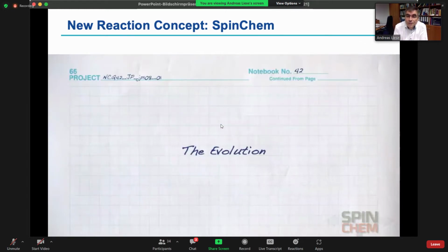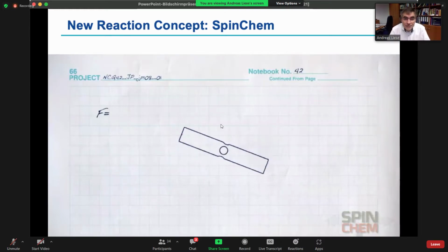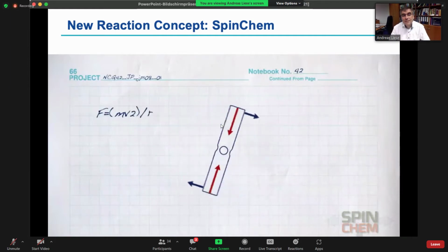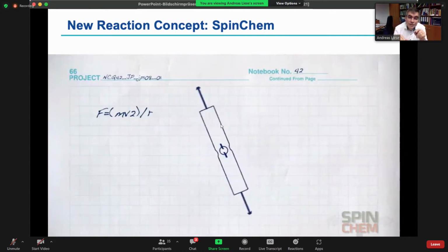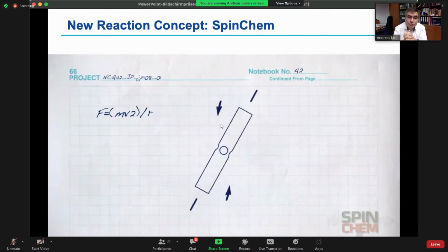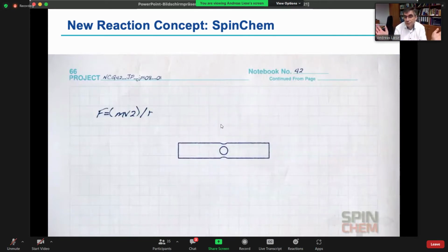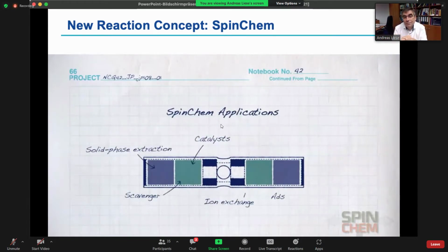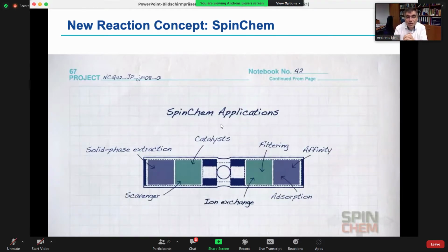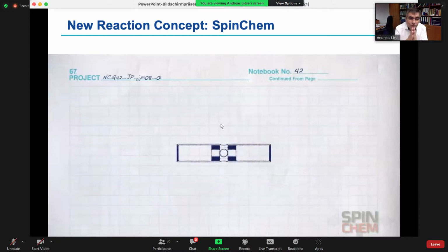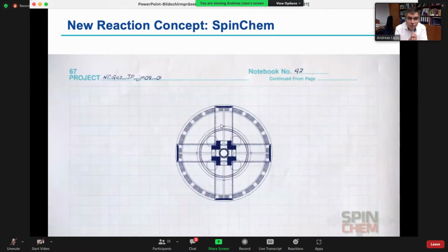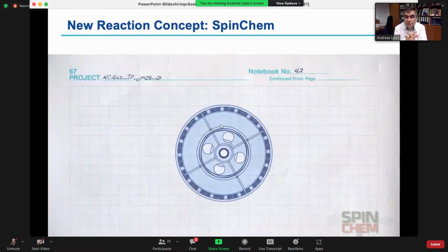And now, where do we do the evolution from a stir tank to the fixed bed reactor? This magnetic stirring bar, in the end, is a hollow pipe. And if we stir the pipe, we can draw in solvents from the middle, which will be pushed out to the outside. Now, if we would fill this tube with packed beds, in the end, we would have a stirrer that is stirring and then convectively installing a flow through the packed bed to the outside.